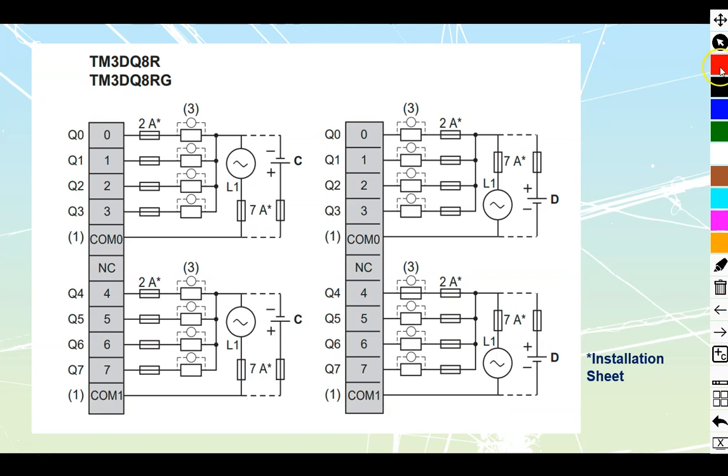The next thing that we look at is going to be our wiring diagram. Now, our diagram over here does have 2 separate drawings. We need to analyze which one we need to use because we're not using all these drawings at the same time. They're just trying to illustrate everything at once. First of all, we're going to scratch out a couple components that we know we're not going to use by defining which side is going to be sourcing. If I take a look, sourcing is going to be applying a positive to the common, which then switches through out to my components.